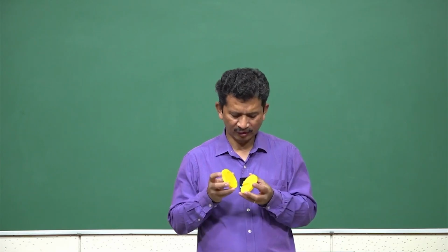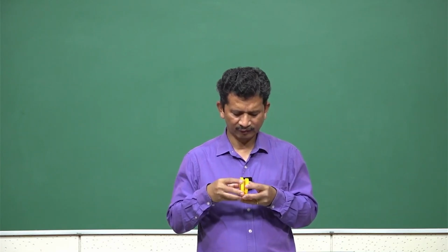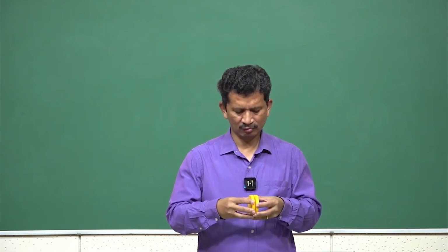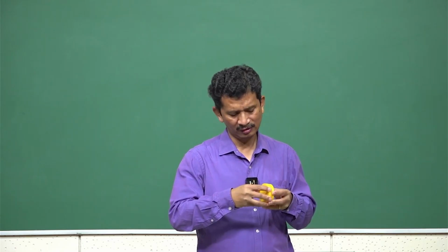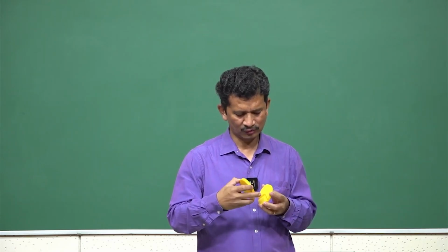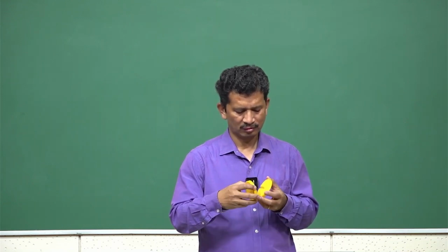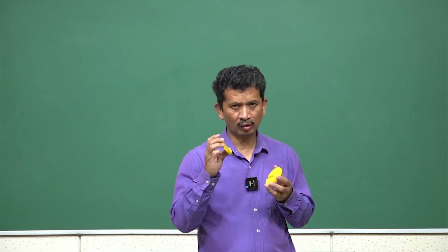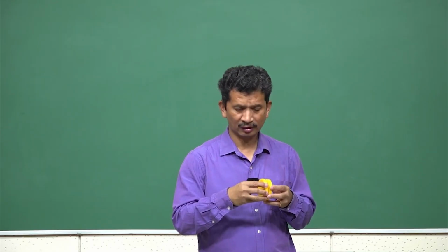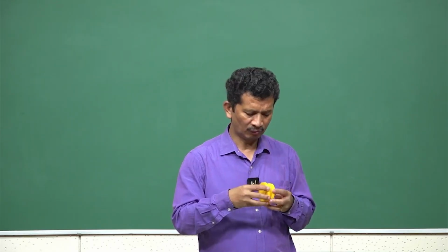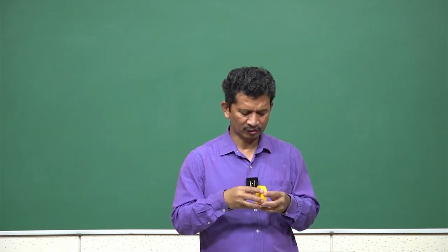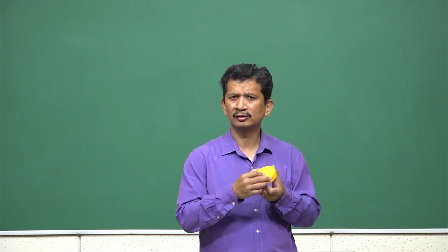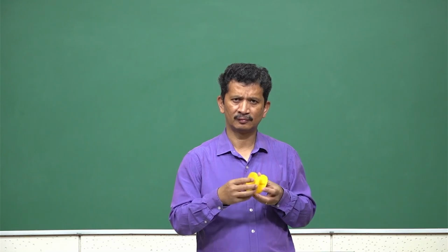We can again see one by one two contacts, and if we make two contacts, it can rotate actually, because these two are very similar to two V and the two ball. So, that motion we will have. The moment the third one contacts with another V, it will go to the same location. So, I can do it blindly.